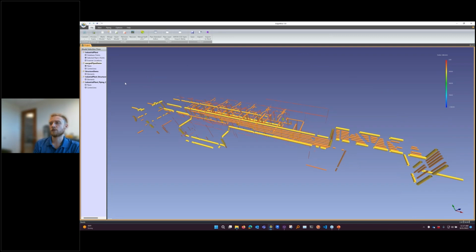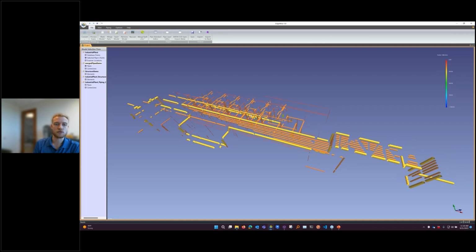and this is going to look for cylinders in the point cloud, and this is where we start. This is actually our start point in the software. What we're looking at here is 0 man hours. This is no time other than just me putting the point cloud into the software and hitting run, and then an hour later, this is the starting point. It's something that we can really get a huge jump start into our modeling process with this workflow, because the software really can do some of the heavy lifting with getting that initial model created.